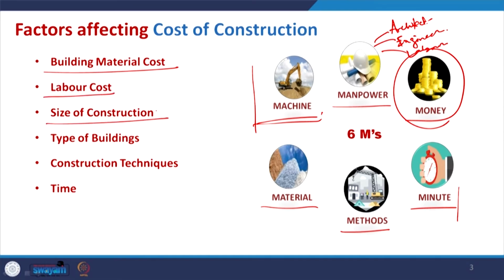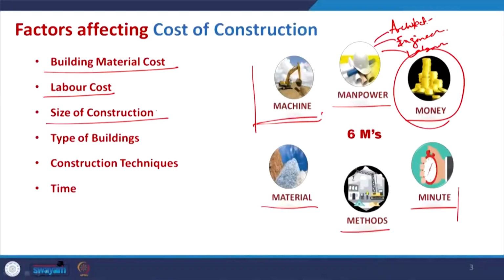If you think of precast or prefabricated elements as construction material, that means it will not be cast in situ. It is fabricated somewhere else and it will be just a plug and play kind of arrangement. In that case, for a small construction, it will not be cost effective, because you have to have an area where this prefabrication can happen, and you need some kind of machinery.